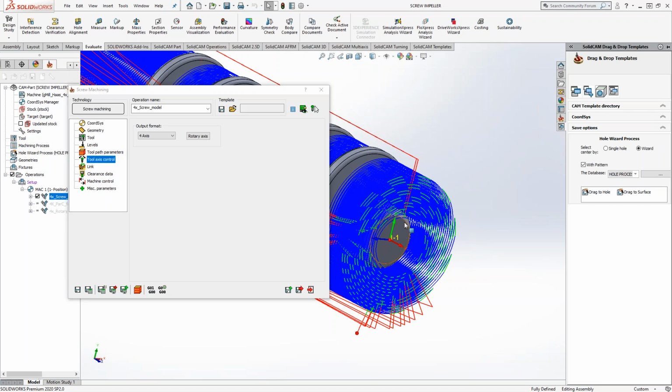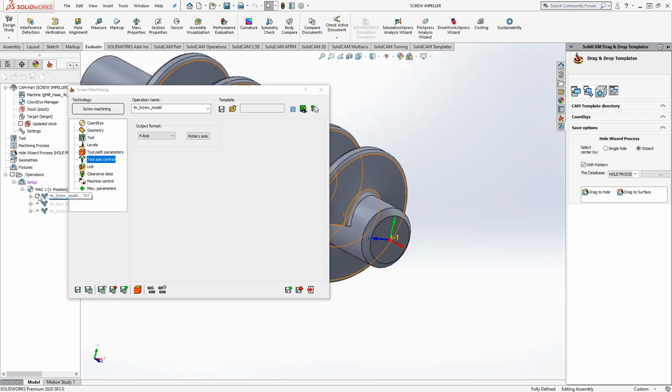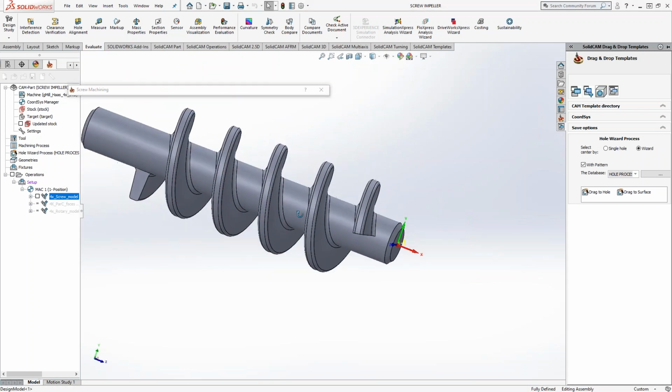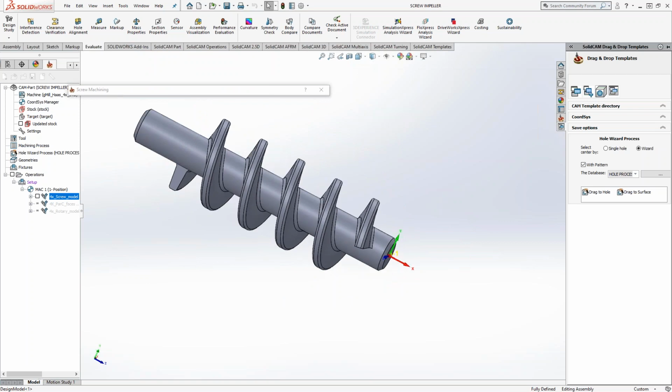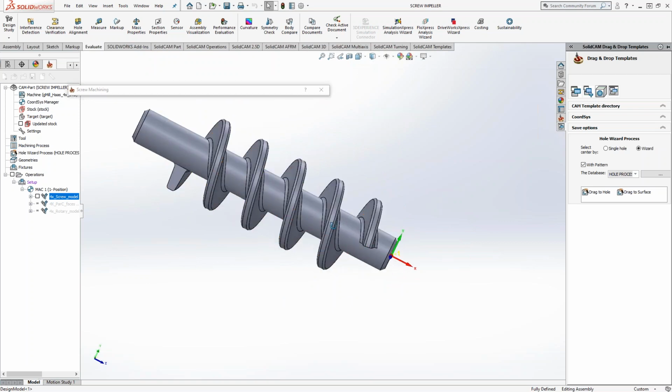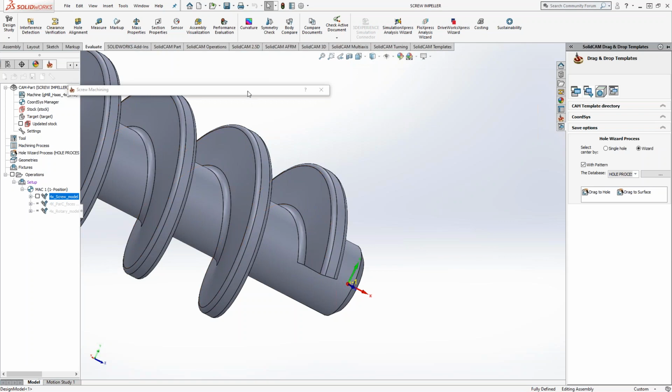That is what I would show people before this toolpath came along, or to be honest, before this toolpath calculated this fast. Eye machining is always a good idea. Right now, we don't have a rotary version of eye machining, or a rotary screw machining, but it is a great way to reduce your cycle time and machine out a 3D solid. If you don't look at this as a rotary part, all we have to do is have an index angle, rough out all that stuff, and then come in with a nice simultaneous 5-axis toolpath, maybe a Swarf toolpath, something like that.